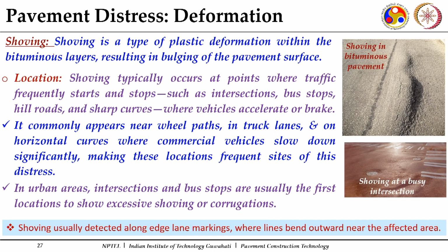Now, the other form of distress under the category of deformation is shoving. You can see the mix is pushed to the side. There is a bulk quantity of mix which is pushed to the pavement edges. Here also you can see the mix getting pushed towards one side. Even the pavement markings get disturbed; you can see the pavement markings have become wavy. From there you can get an idea that some shear failure of the mix has happened, there is some shoving.